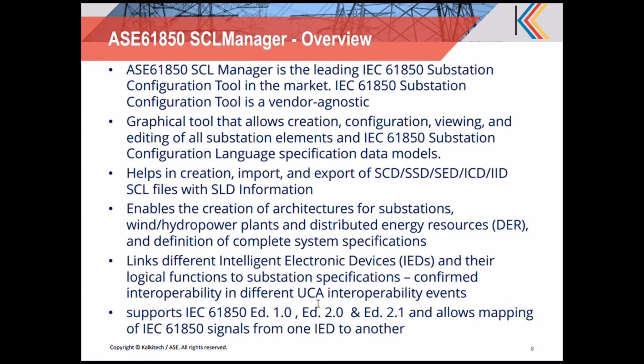interoperability with all vendor tools. So this is a completely vendor agnostic SCL Manager. It also supports versions 1, 2 and 2.1, and allows mapping of 61850 signals from one IED to another, and doing the complete testing and configuration. Everything can be done using the SCL Manager. So it is a complete engineering tool, all the engineering of 61850 can be done.